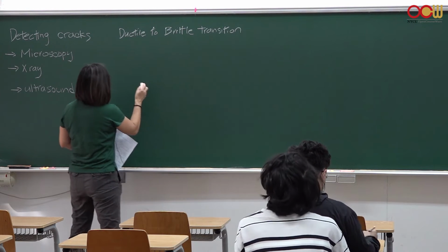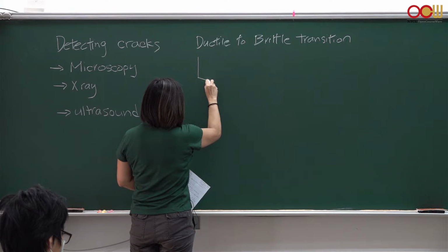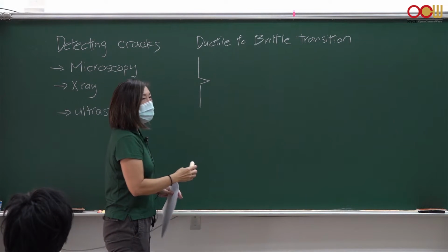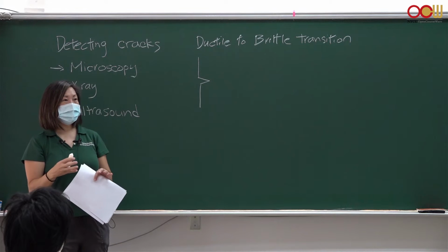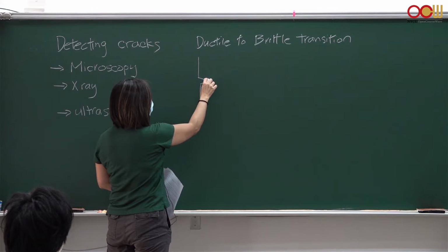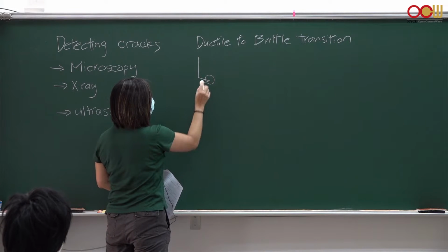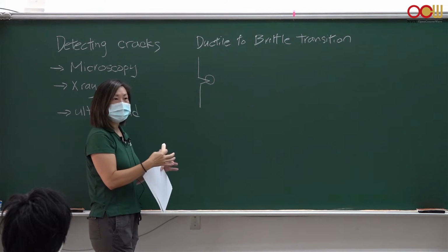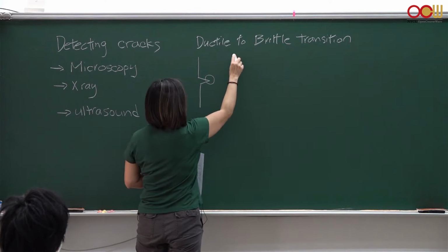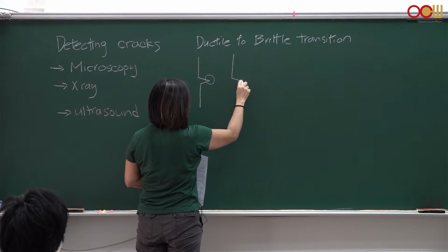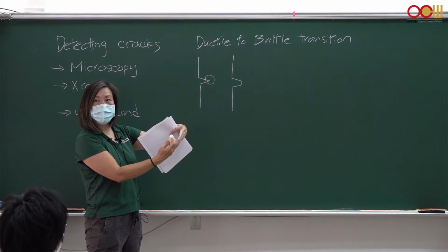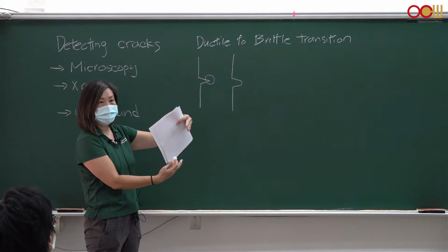So in a ductile fracture, if you have a crack like this, right, because the material is able to allow for a slip or dislocation movement, the tip where most of the stress is concentrated will experience a large amount of stress at the tip. So it will start to blunt. It's going to start to pull that tip apart, and because the slip is able to deform, right?